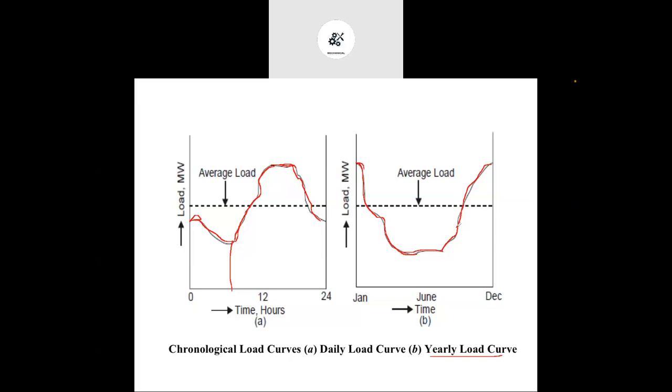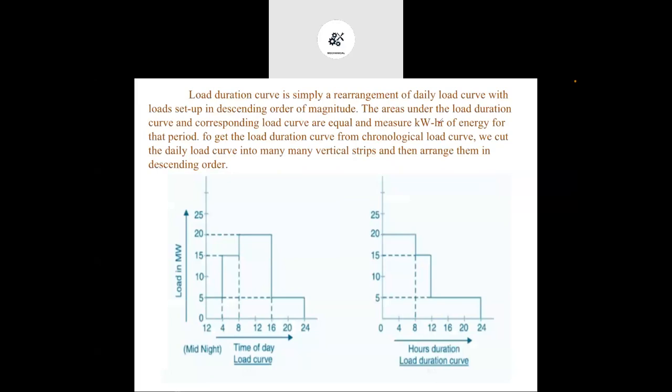It also depends on the weather, how much electricity is required. It is also going to change with respect to the customer. So there are many other factors which are going to affect whenever we draw one particular load curve. But it is important, because we get the idea from this load curve of what type and how much electricity should be required. So during January we require maximum demand. The generating company uses this particular data to plan to produce the particular power.